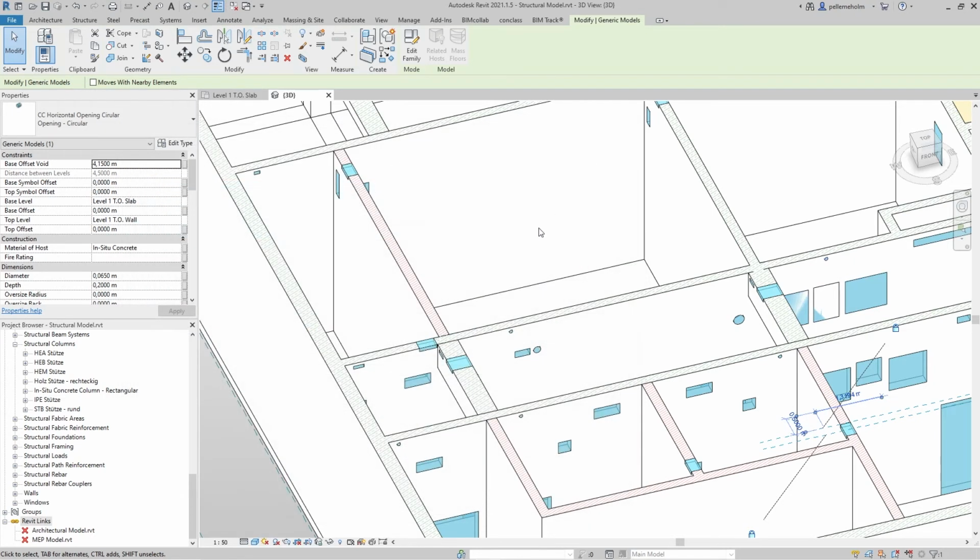The reason why is when you are working with dimensions in a 2D plan. It often happens that you catch the reference of the wall and not the opening. If the cut disappears or the opening gets moved, the dimension may be deleted. You can avoid that by keeping the opening uncut, because then you can be sure that the dimension will have a constraint to the opening and not to the wall.